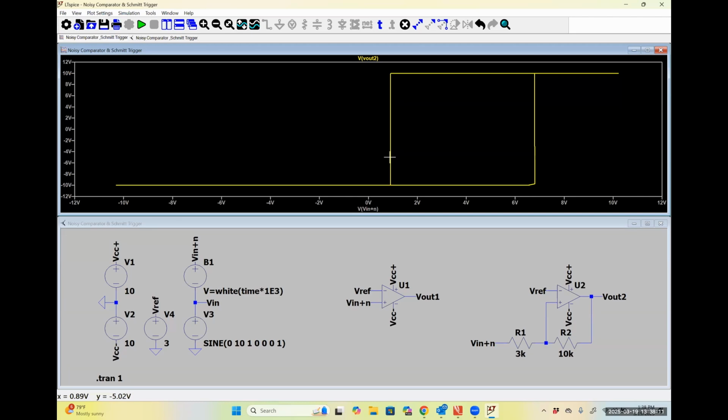And then it's going to saturate at VCC plus until we hit positive 10 volts, and then we're going to back off that voltage. So it's going to stay here at VCC plus until we lower the voltage enough so that we go lower than the lower trigger limit, and then it switches back down to 0. So the way that this is going is from left to right along the bottom, jumping up, continuing to the right, then going from right to left on top until we hit our lower trigger limit, jumping down to the bottom, and then continuing to the left.